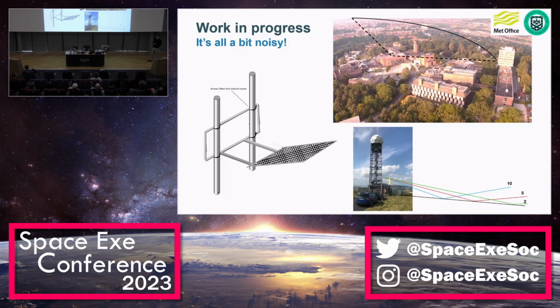One of those problems is that we only really care about the direct signal from the aircraft. This is the signal that's undergone refraction, and it's the one we want to measure. But the problem is we've got all this stuff in the foreground, which is quite reflective. Radio waves bounce off these buildings and are received by the antenna, and they contaminate this direct signal. It completely scrambles the data. So ideally, we want to block these signals from interfering with the direct signal.